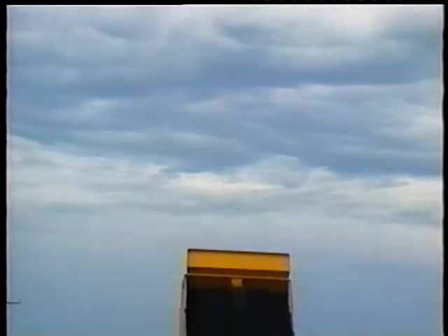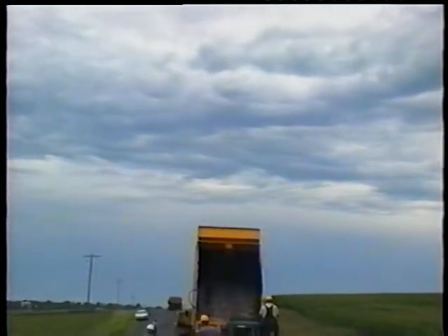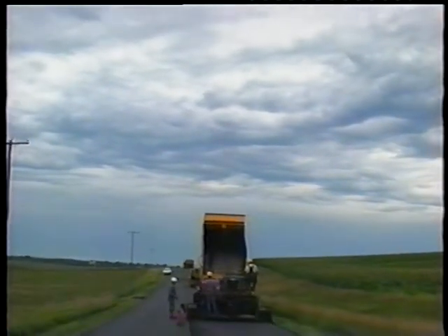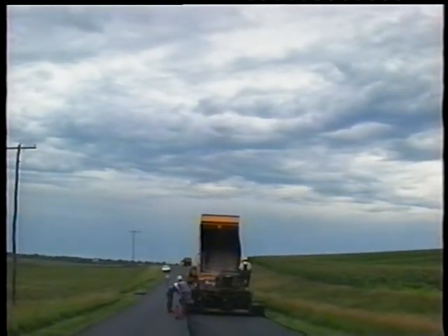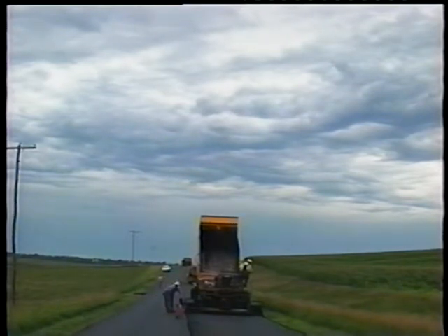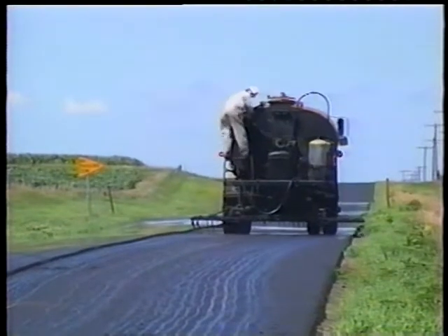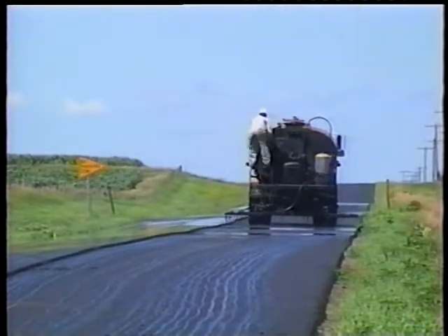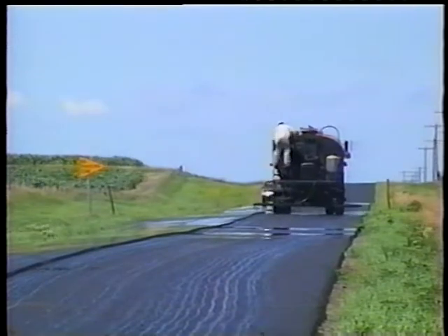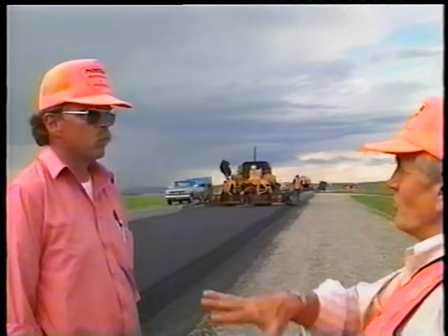Precipitation is a concern. Asphalt paving should not begin when rain is about to fall or too soon after it's fallen while the surface is still wet. Occasional sprinkles or passing showers have to be dealt with according to their volume and duration, from working right on through the minor ones to temporarily halting for the more serious ones. Winds by themselves may not be cause to avoid paving, but they sure can mess up the tack application and cool down the mix real fast. So use good judgment. If weather conditions prevent good work, take the necessary action.